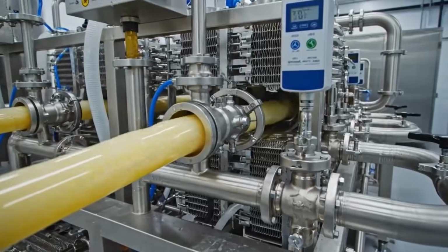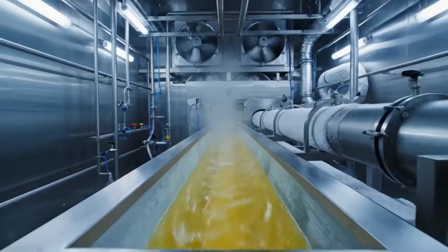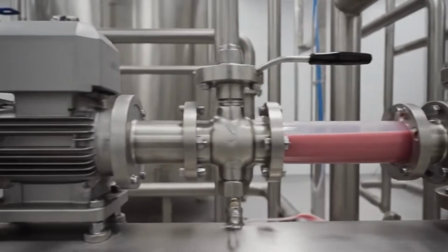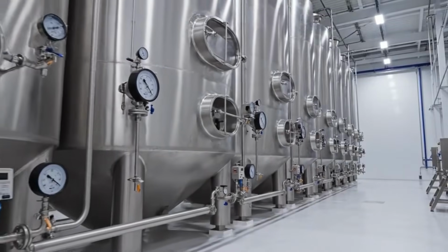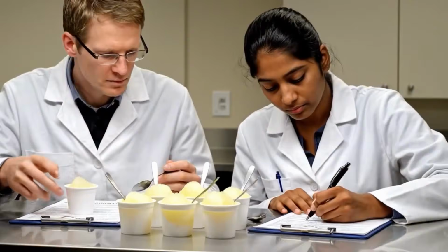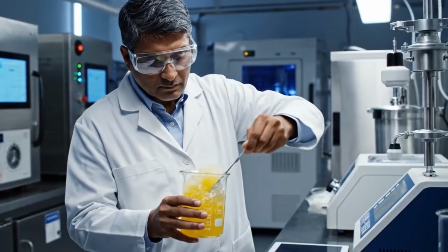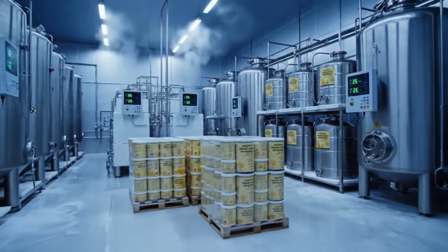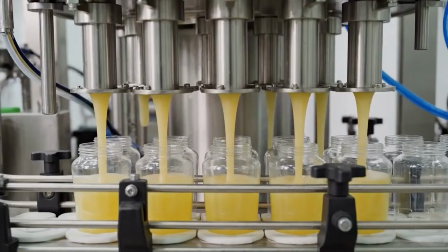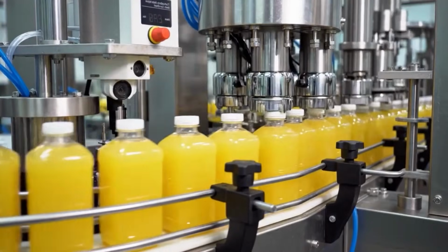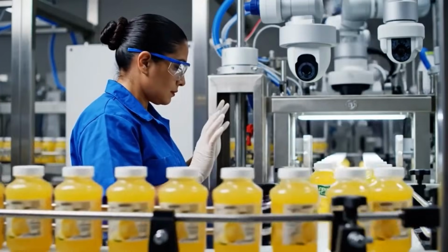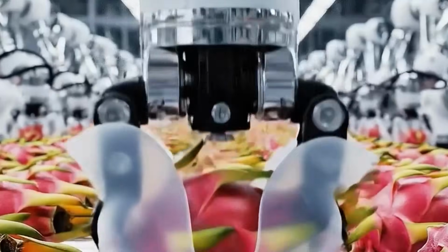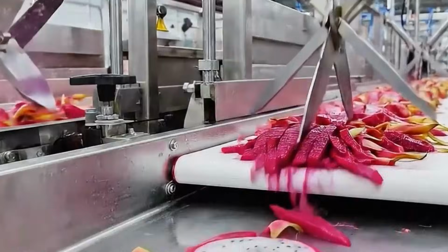At the point of extrusion, some product formats receive inclusions or variegates. For inclusion, dry or semi-moist elements like fruit pieces, citrus peel, or coconut shreds are fed through a belt-based dosing unit with weigh cell feedback. The feeder aligns with the product stream and deposits inclusions just before it enters the filler. Variegates, such as raspberry swirls or mango sauce, are injected via multi-nozzle swirl heads using positive displacement pumps, synchronized with container indexing to create layered or spiral visual effects.